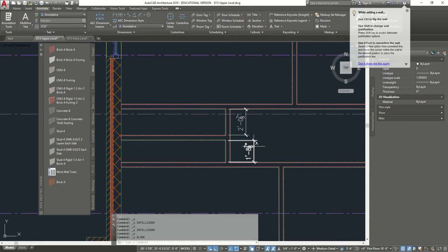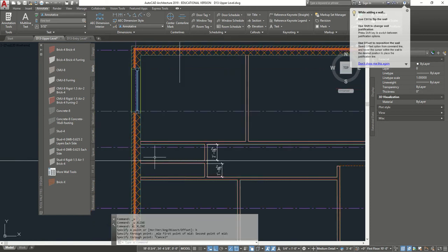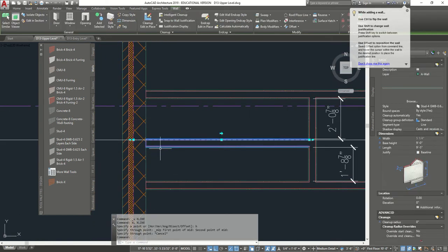Hold on. So something went wrong. It could be the way it's justified. So what to do to fix it? Just draw an X line. Horizontal. And again, we'll get the midpoint again. So do control midpoint between 2 points. This time I'll use this side. 1, 2. And we notice it grabbed it over there.